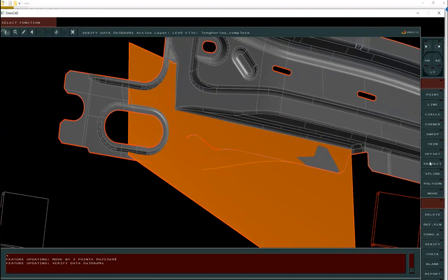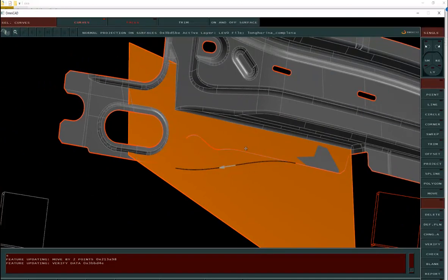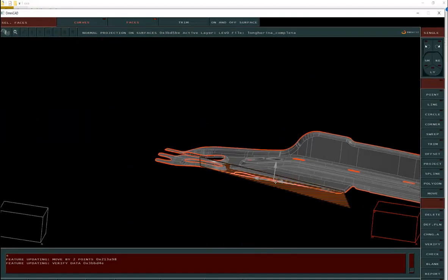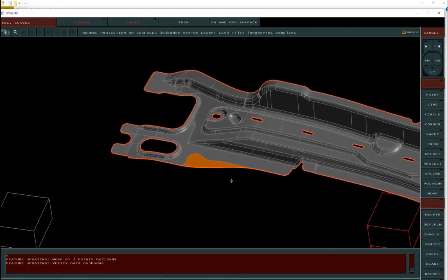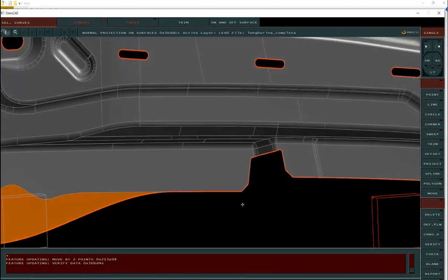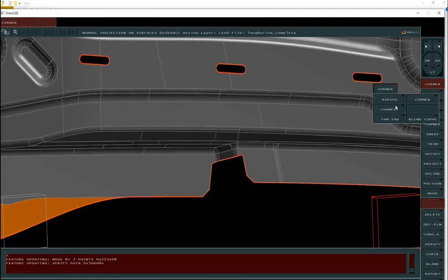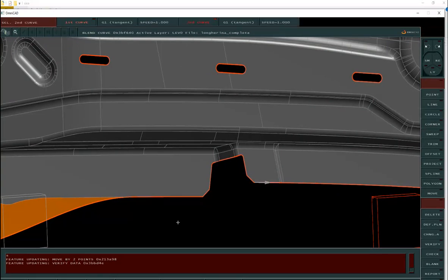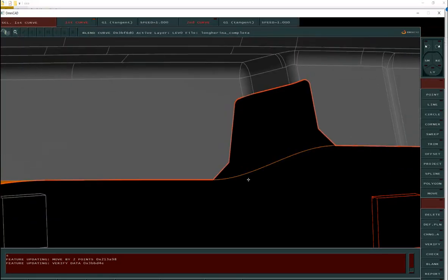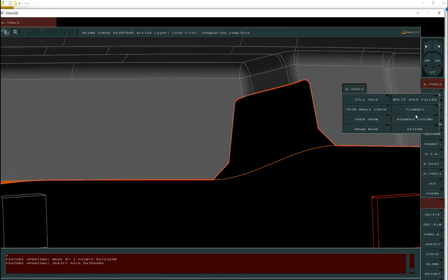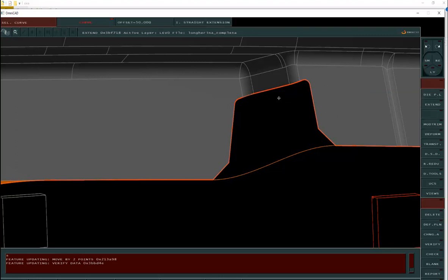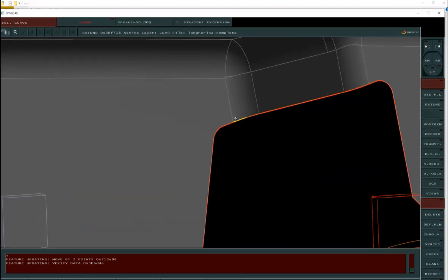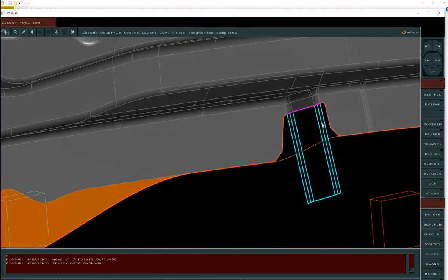of this profile. Project, surface normal, this, and keep zone is internal zone. The same here, I can use a corner, bend curve from this profile and this other profile, and here I will use a new tool of die tools, and it is extend, and I use from this profile to this other profile. I want to extend the surfaces.